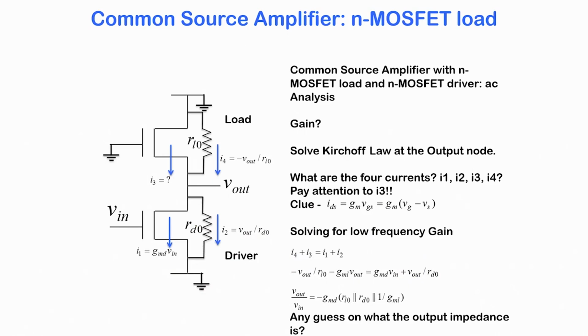So, the small signal analysis is like this. That was the load MOSFET, that is the load NMOS transistor which is sitting in saturation. This is the channel length modulation resistor of that load, and this is like an ideal NMOS transistor, and in combination they give you the non-ideality effect. And the gate is grounded because this was a DC bias signal that we had applied. So, that is AC ground, and now we have a small signal AC V in into the driver MOSFET, which is also an NMOS which is in saturation.